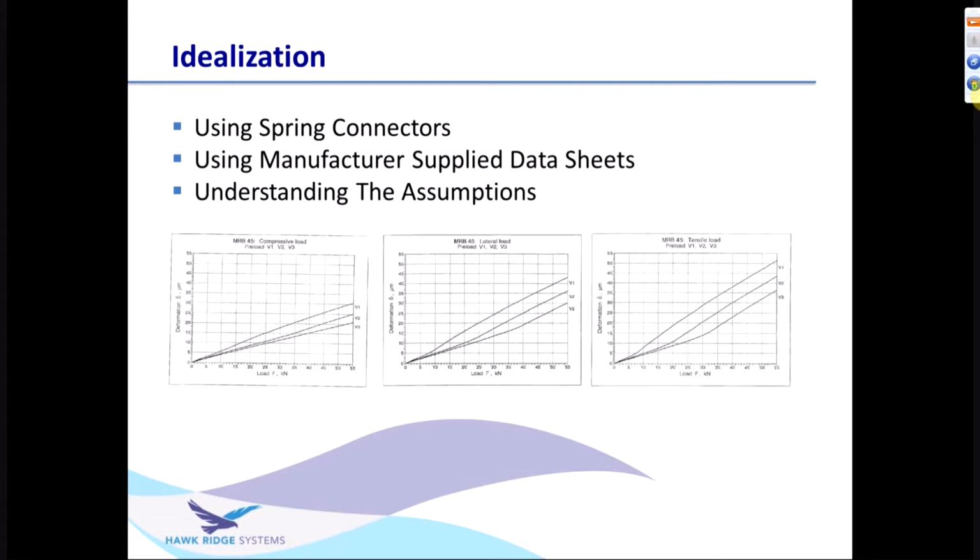And you can see in the slide here that we have 3 different data sheets representative of the different loading directions that the trucks or the linear rails gave with regards to deformation versus the load being applied. And then for the ball screws, we were given just a single rigidity value, and I'll describe how we used all these in a moment here.